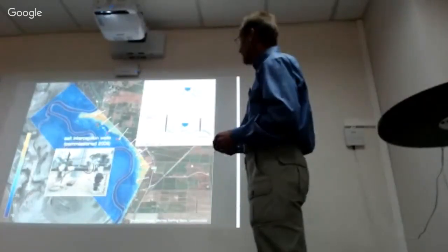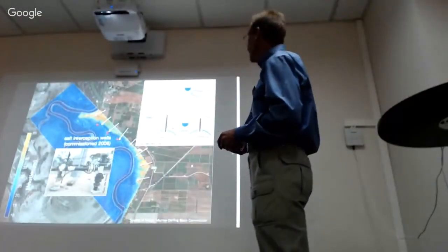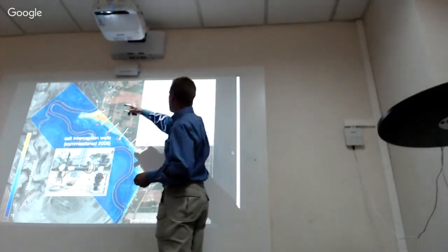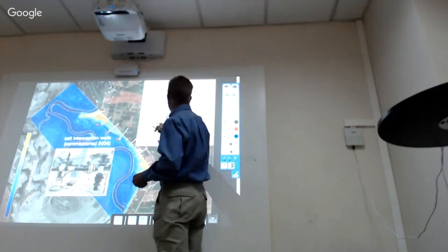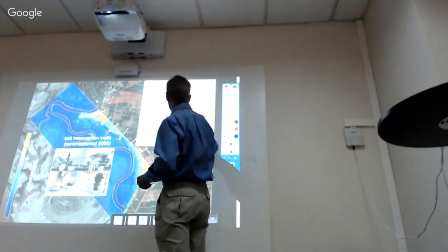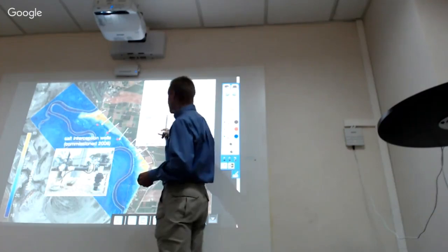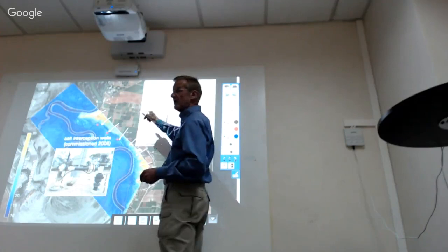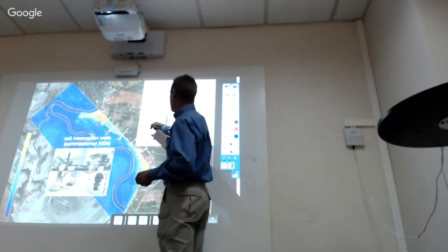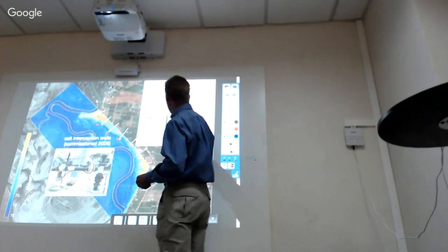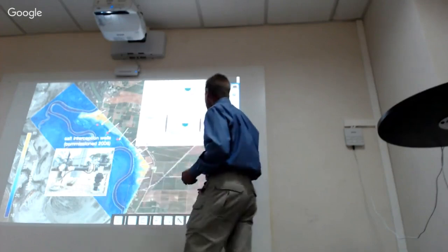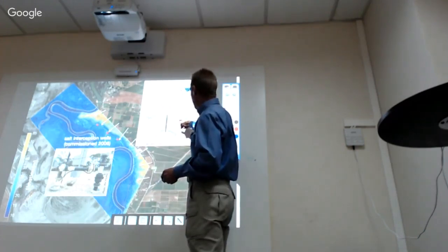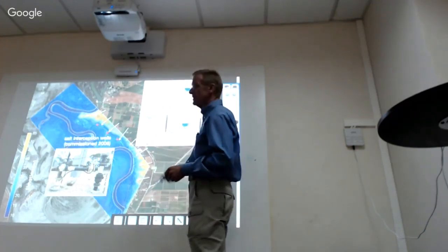They would drill a couple of wells here, and they would pump water out. So this is kind of a cross section. Here you're up on the irrigation region, and so here's the land surface. Here's the river. So you drill a well, and you pump water out, and then you store it up on a reservoir up here, and then that's supposed to evaporate, and then you're just left with salt. So that kind of pulls salt water out here. At the same time, you might inject fresh water in another region in here to try to push the salt water.